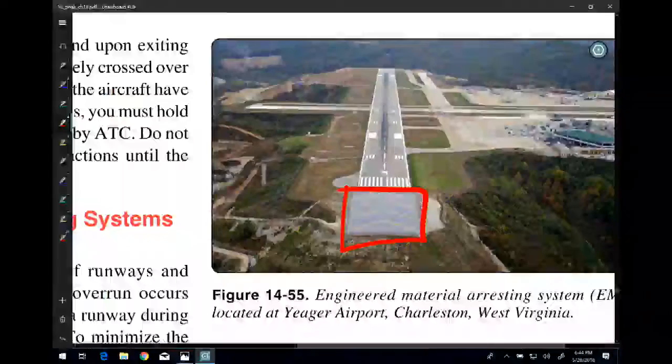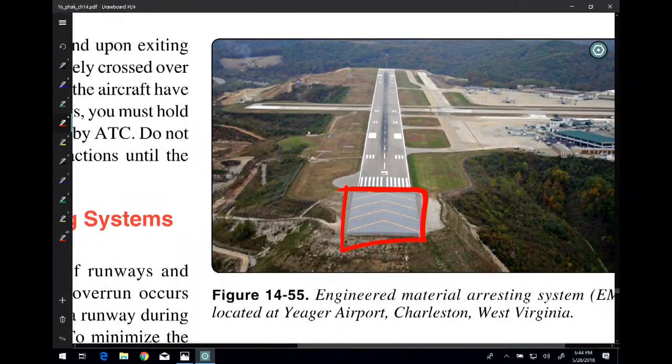So when you look at this here, one thing I want to show you is this. Where's the taxiway to come over here and use runway 5? Well, look where it is. The closest taxiway that you have is over here. Well, how do you get over here and take off? Well, you'll notice this little piece right over here. This is what we call a turnout. So what you do is you are going to enter the runway here when you have permission.